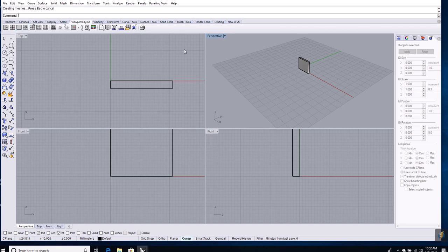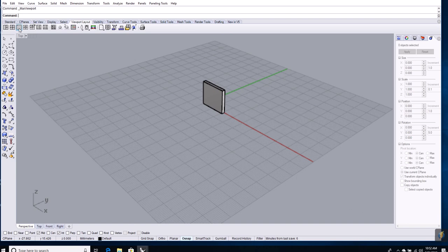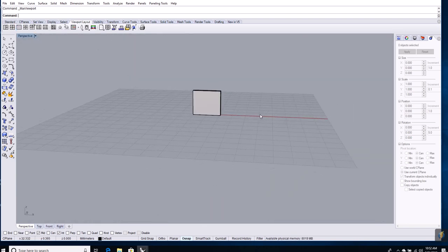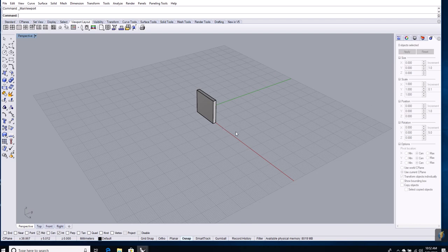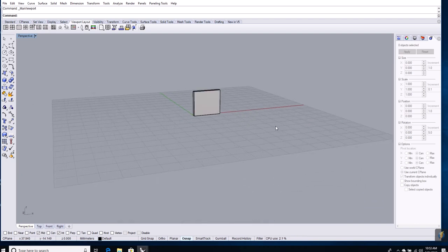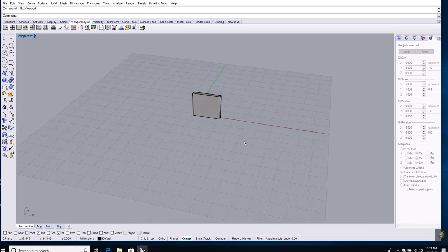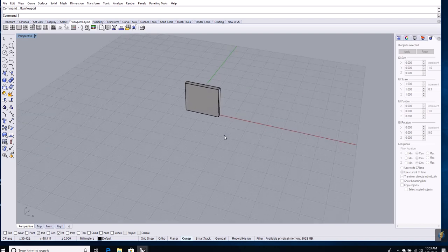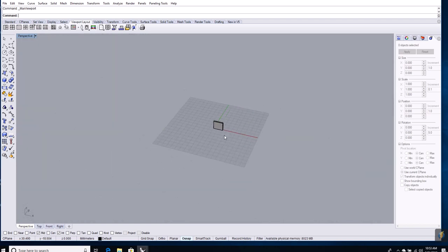So to change it up, I've selected perspective, and then I hit the one window, and then this is where you can zoom in and be able to move around. So the first thing you want to do is just get oriented where you can function in this environment. You can look at your models, you can zoom in, and you need to use a mouse that has a wheel on it, because zooming is from scrolling the wheel.